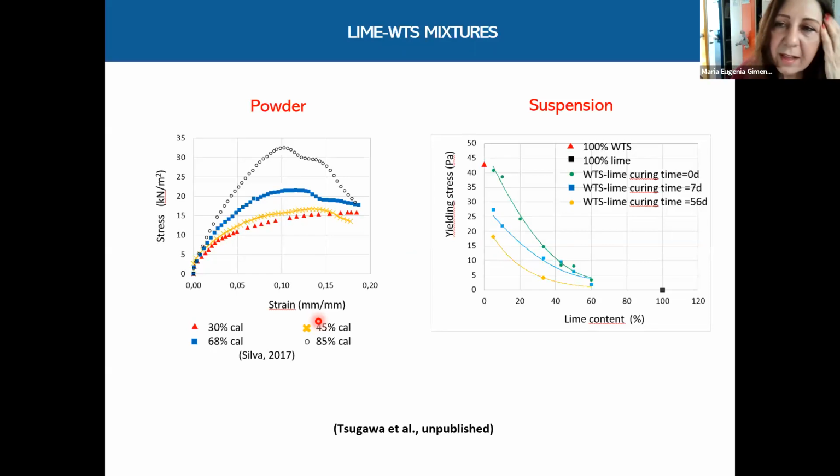Finally, here there are some results of lime sludge mixtures. Here the lime was added as powdered, and here as suspension. The tests here were unconfined compression tests, and here rheometer tests. In the first case, the results are as expected. The strength increases with lime content and with time.